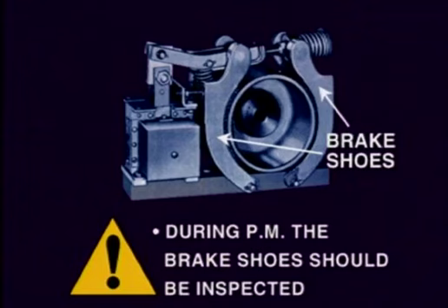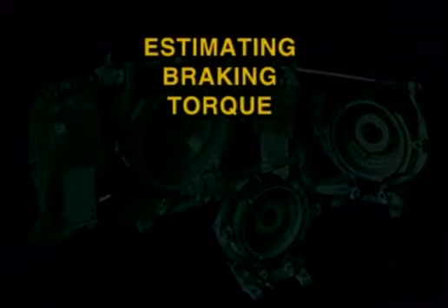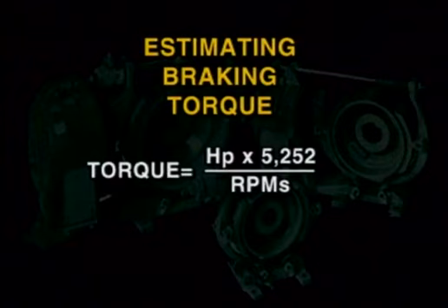During preventive maintenance, the shoes of the brake should be inspected to ensure that they are not worn out, and replaced if necessary. If you need to select a friction brake, it will be necessary to choose it by taking into account the amount of torque of your motor.